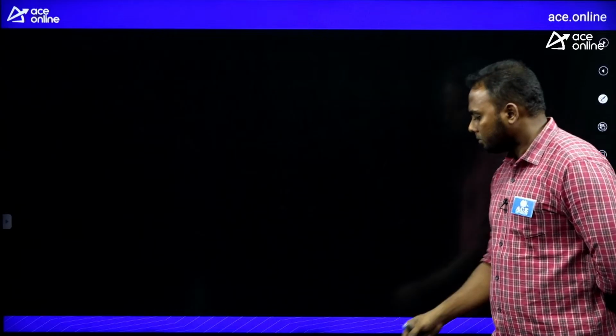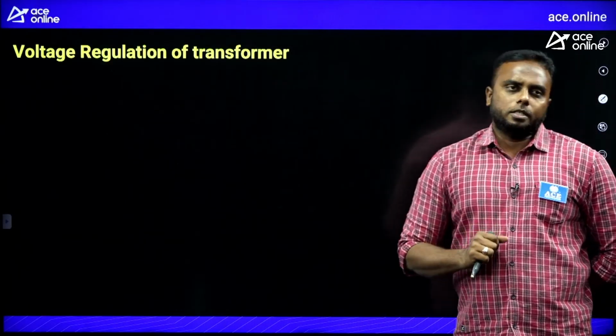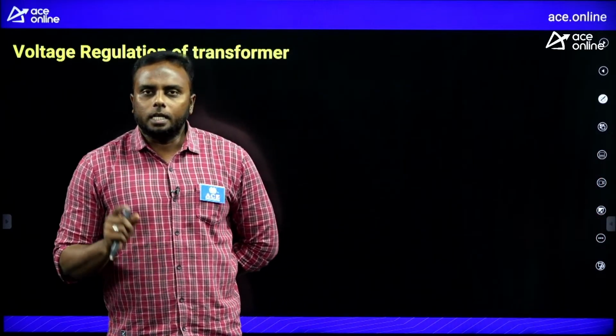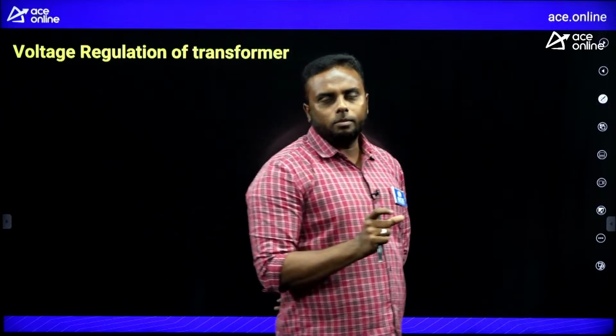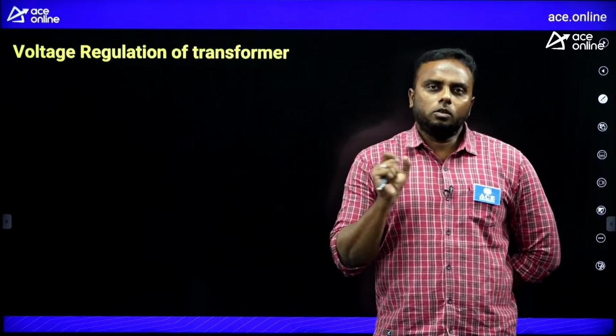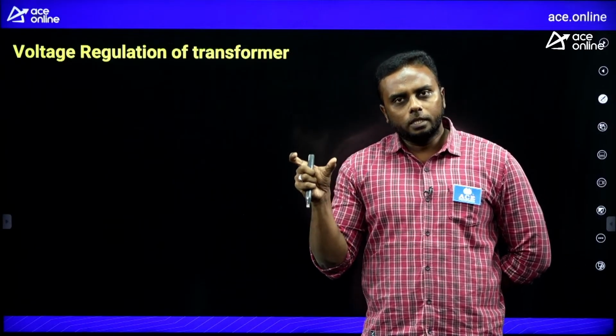Next, voltage regulation. So this is important. Here, mainly the conditions for voltage regulation are important. Condition for maximum regulation, condition for zero regulation. And where will regulation be zero? Where does regulation generally become zero? At leading power factors we get zero regulation.